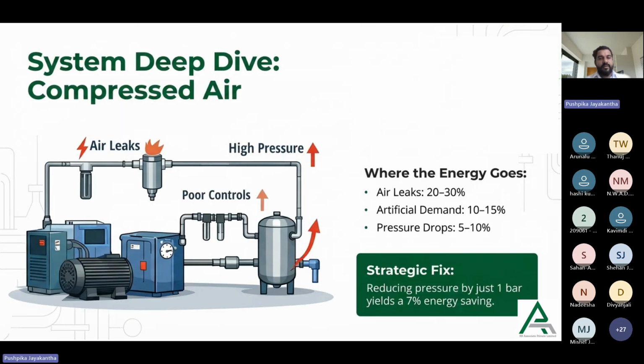The next one, air compressed systems. We describe this as the most expensive utility in industrial facilities. These inefficiencies can happen due to air leaks, pressure drops, improper compressor controls. Regular maintenance and system optimizing can significantly reduce this energy consumption.